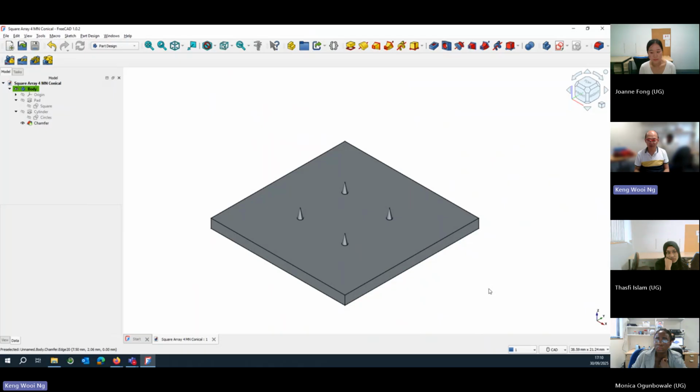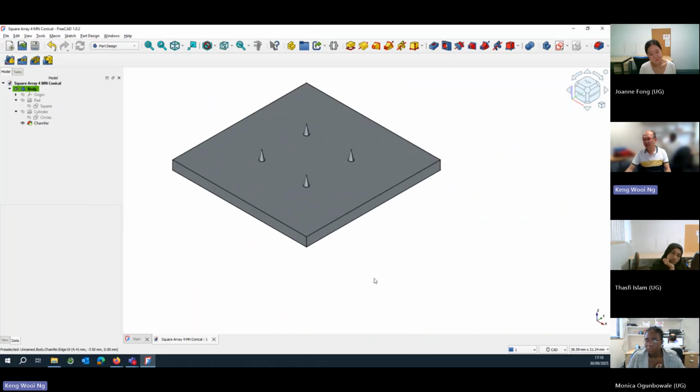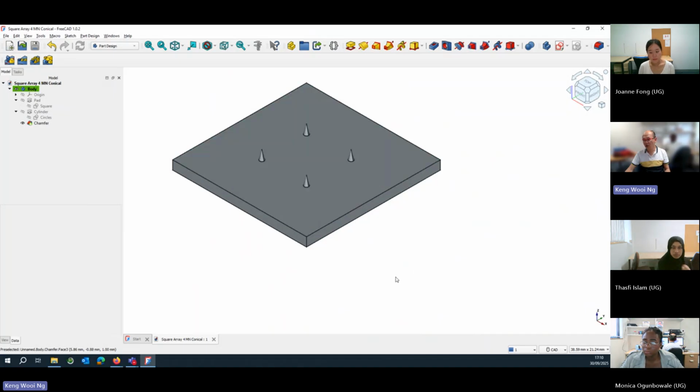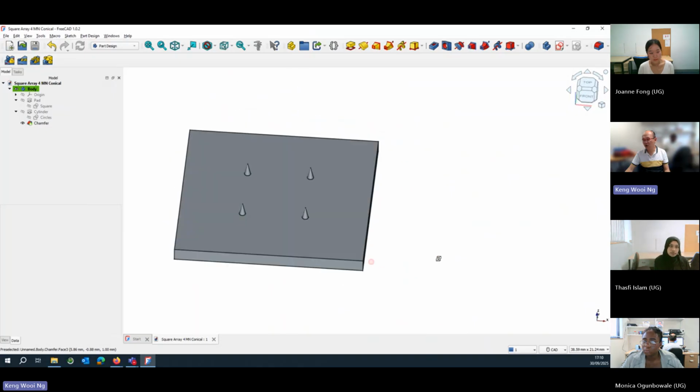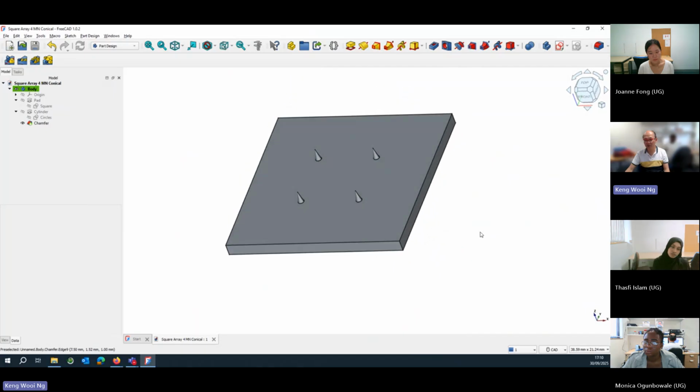I recommend doing a bit more to the design. Like, for example, if you're using this for microneedle biosensing and different needles have different functions. So, for example, if each needle would detect a different antigen, then the orientation of the patch is important to you, right? In this case, there's no way to tell which side is which. Like easily, this could be the top, or maybe that one could be the right hand. Because when this is a real printed object, there's no way to tell one side from the other three sides. They're all the same.